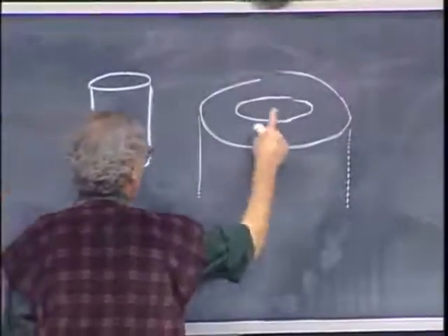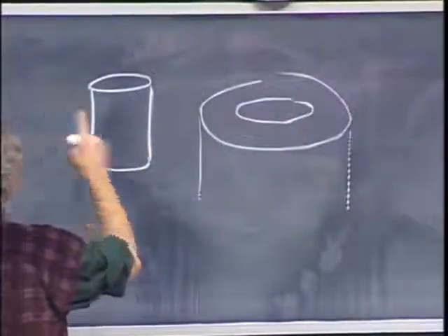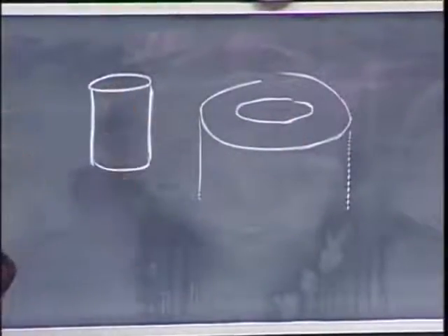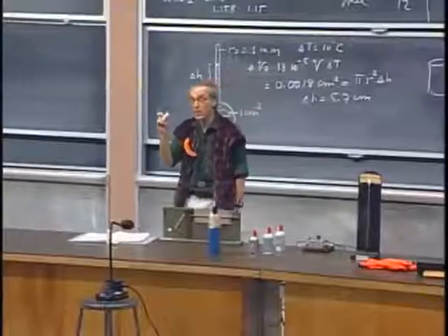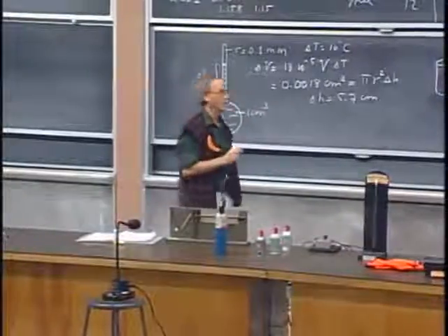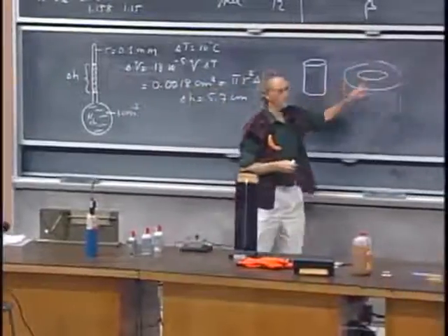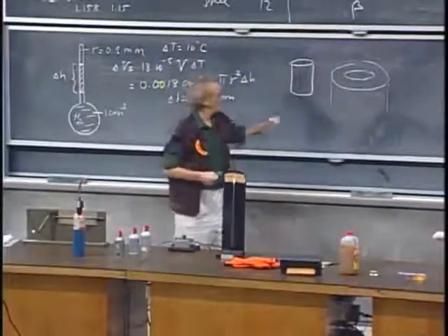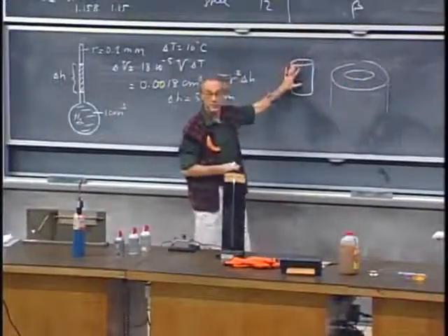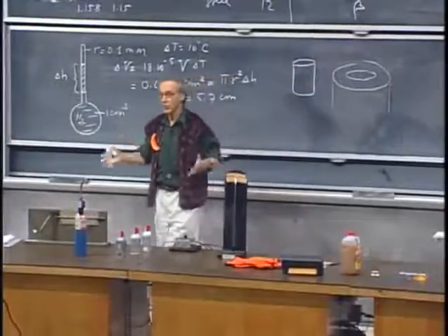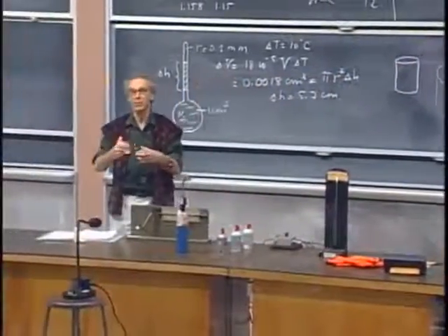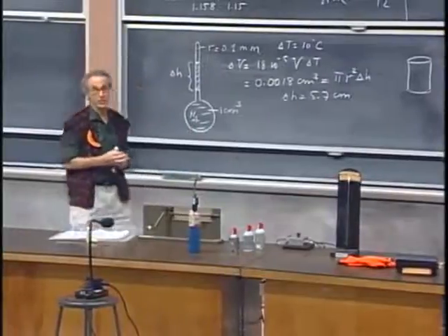This opening is smaller than this. Just a little smaller. Purposely made that way. You heat this one, it expands, and then you put it over here, it will fit, and then you let it sit, it cools, and it tightens itself up. That's called shrink fitting, a technique which is often used.